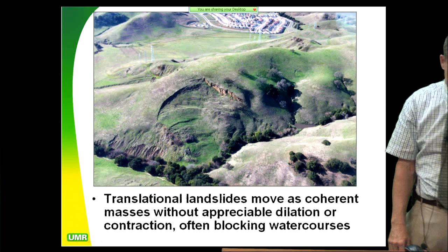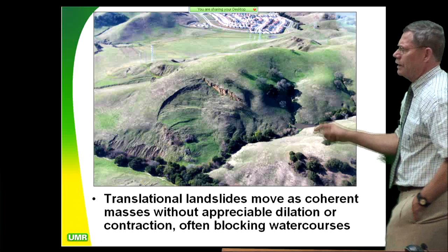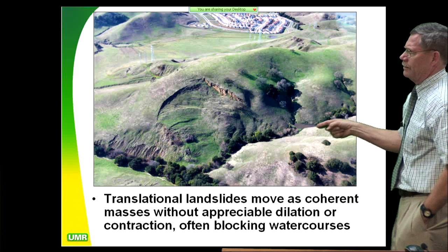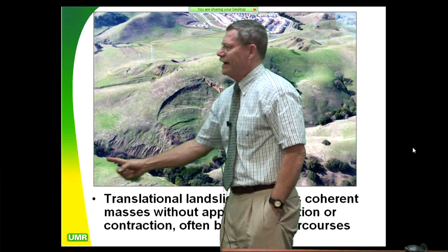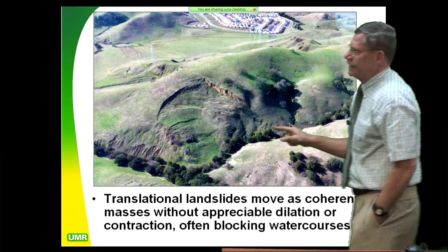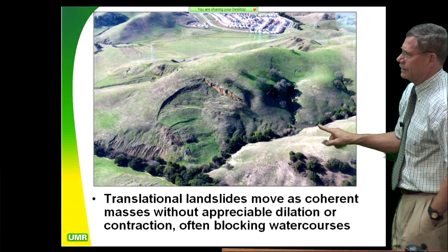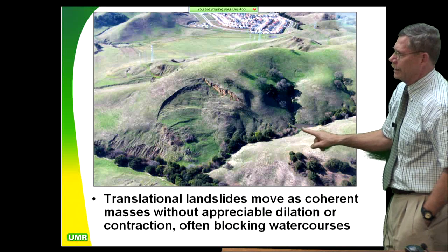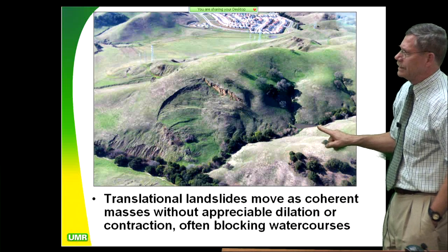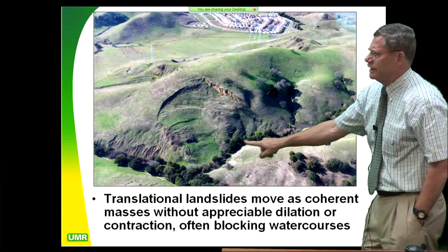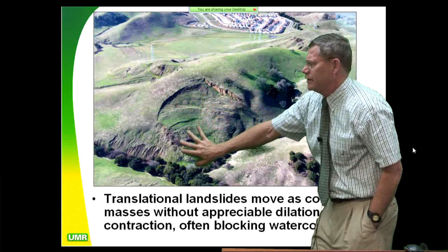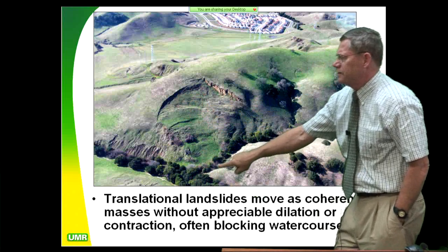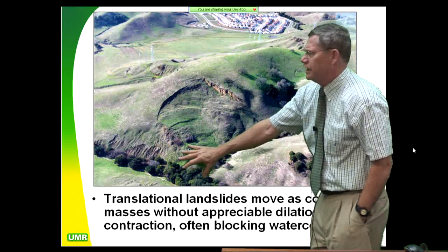Here's another one, very, very active one, where you have a channel coming down. It used to come straight through here like this and out over here. And you can see there's a lake right there with a lot of muddy water in it, telling you you have dispersive clays. And then there's another series of muddy lakes along here. And this is the blockage. The blockage came down right into this confluence here between these two channels and plugged it.